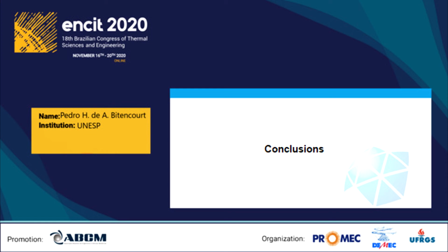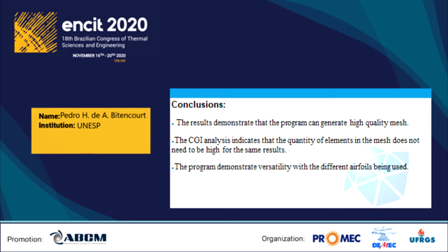Now I'm going to present the conclusion. The results demonstrate that the program can generate high-quality meshes, since the results obtained using the structured mesh generated by the proposed method have approximately the same results as the literature for the two different cases. Also, the GCI analysis indicates that the quantity of elements in the mesh does not need to be high to obtain the same results, the number for both cases being approximately 2 million elements, reducing the computational cost to simulate the case. The program demonstrates versatility with the different airfoils being used, and with the good results, it reinforces